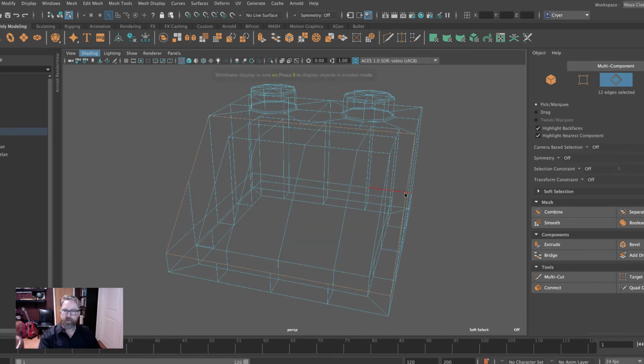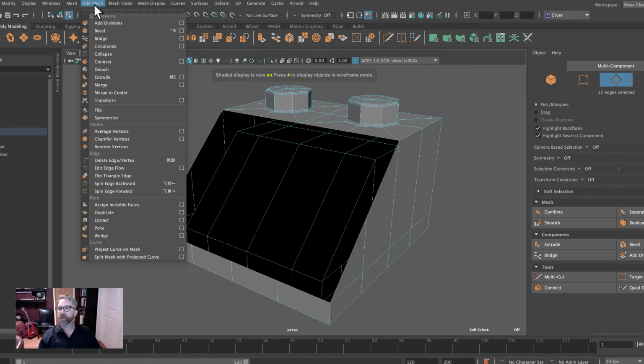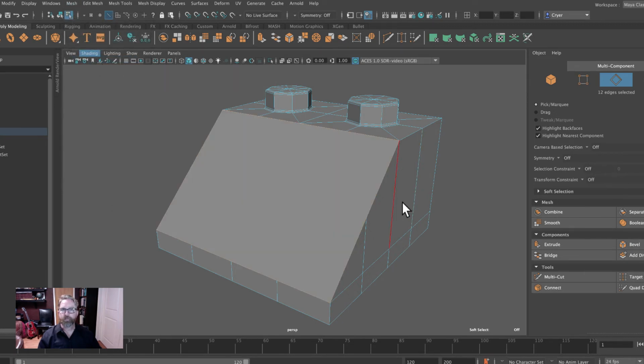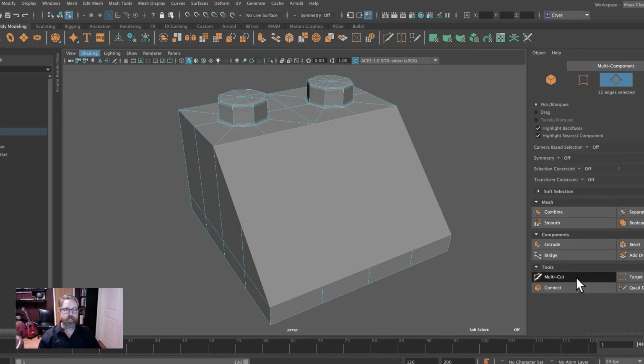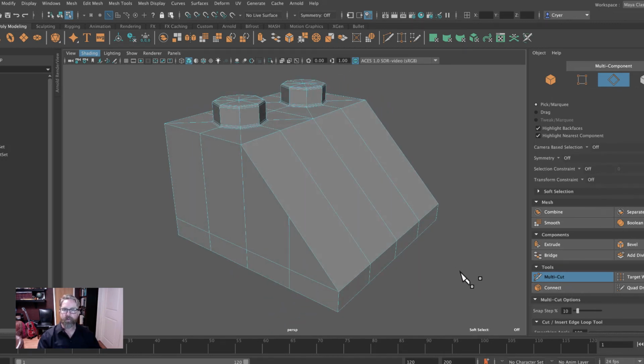We'll select that edge, double-click that edge, and we'll come to Edit Mesh, Mesh Fill Hole, and then we'll complete these edges. We'll click, drag, enter, click, drag, enter, click, drag, enter, and we have the same circumstance here. We don't need to draw across. We'd still be left with this triangle.